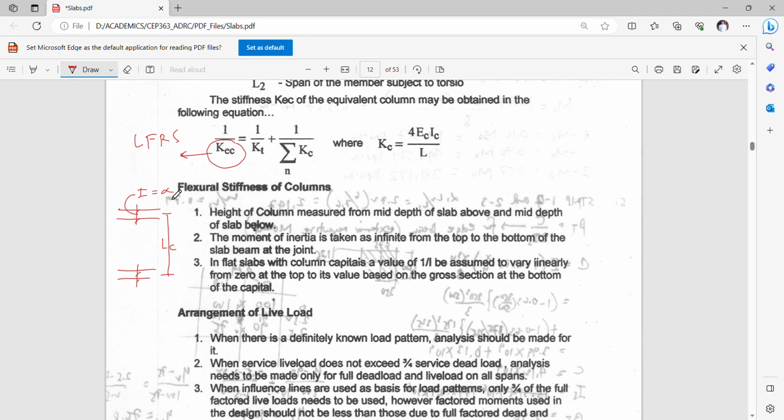How do you put an infinite value when using software? So you just create a big value, a value that is maybe 10 times greater than the other elements, to represent an infinite value. Because you cannot, of course, place the numerical value of infinite in terms of a real number. So you have to put some multiplier to make that parameter produce calculations representing infinite values.